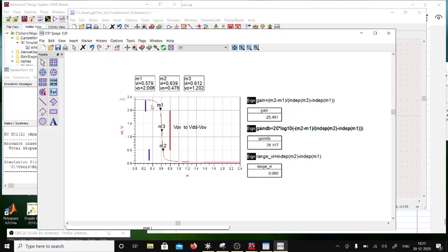And the first problem is that the V overdrive is basically limiting the swing here. That's why we had a wide swing cascode, right? Because we want to have a wide swing across the output. That's why it is called wide swing cascode, right? So that's the whole idea here.